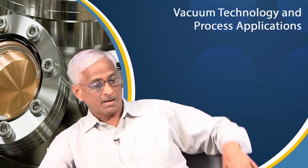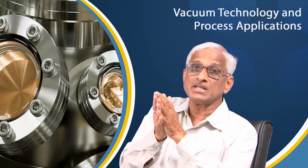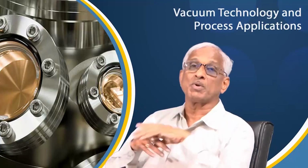So, in high and ultra high vacuum, what you need to concentrate on here is low molecular density, time to form a monolayer, oxidation reduction, and long mean free path. And there should be less degassing from the chambers. The chamber also should be properly designed. Ultra high vacuum is not just producing that level of vacuum. It is the way you make chambers, the way you select the pumps, the way you select the sequence of operation of the pumps, the way you detect the leaks.